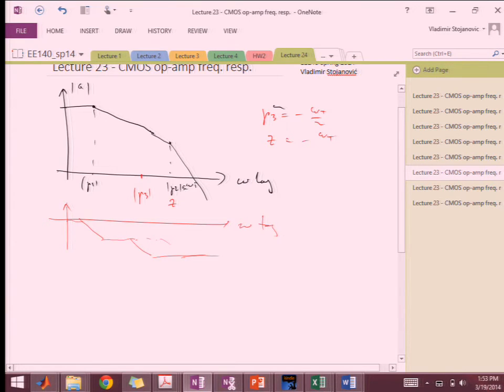So we said that, since this is canceled, now this is my new pole 2, right? And we said that in compensation, everything is going to be with reference to that one, right? Especially in cascode, because I'm now moving pole 1 in cascode wherever I want, because it's kind of independent. Pole 1 is CL dominant.